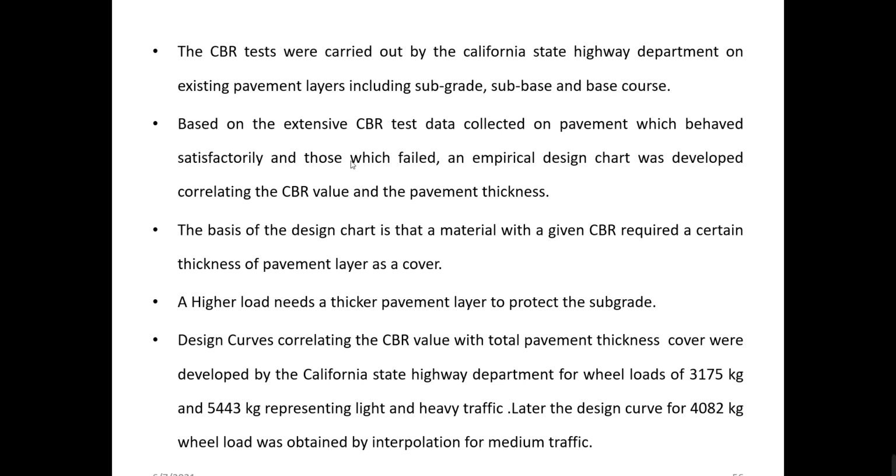They have correlated different types of curves where the pavements have been failing or the pavements are satisfactorily serving the needs of either traffic operation, a military operation, or a domestic operation. So the basis of the design chart is that a material with a given CBR requires a certain thickness of pavement layer as a cover.